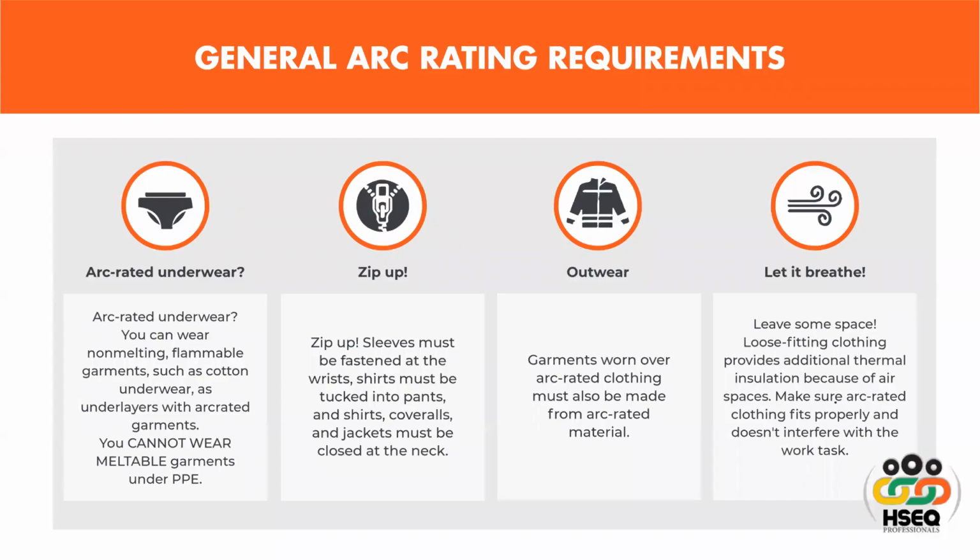Then some other requirements related to arc rated underwear. Those are not mandatory to be arc rated. Normally, cotton underwear, which is non-melting but flammable, can be used as undergarment.